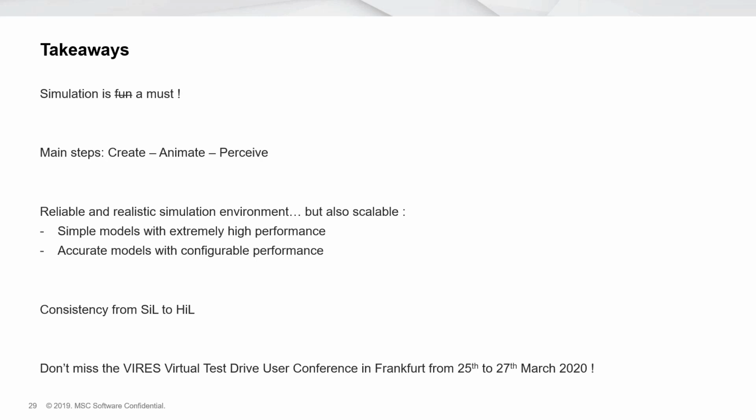Yeah, that's clearly up to the use case. So if you have a hardware in the loop system, or for example a camera in the loop system, real time is the main issue, and you need to deliver images at the correct frame rate so that a real hardware algorithm, which will be part of a vehicle, is getting the information in time. So if you have something like that, you always need to focus on performance, and maybe will have less quality in the images in order to provide images for testing.